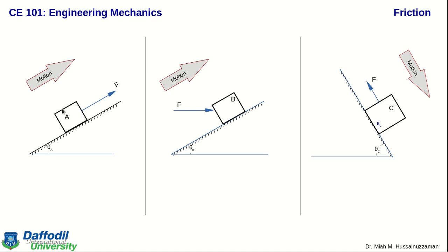First, look at the left figure. To draw the free body diagram, first we have to draw the force which represents the weight W, and then let us draw the reaction force. That means the reaction from this plane to this body. This is a 90-degree or normal reaction, that is why we write it N.